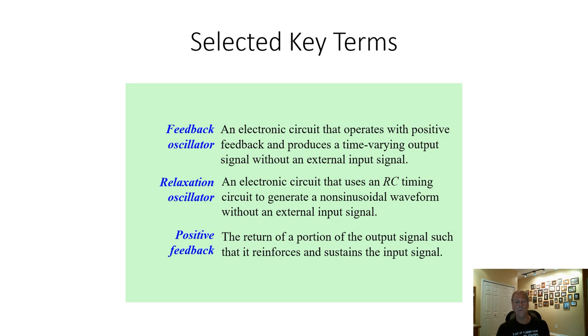You need to remember that oscillators need 0 phase around the loop, and a gain of exactly 1. Otherwise, they will not sustain themselves. Okay, so that's it for oscillators.